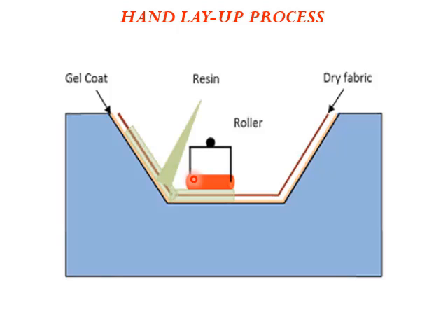So that will ensure the strength of the composite material also. Here the normal matrix which we are going to use are epoxy, polyester or a phenolic resin, which are mixed with the catalyst, which is going to accelerate the process. In order to soften the resin, which will be helpful in compacting the reinforcement with the matrix also.